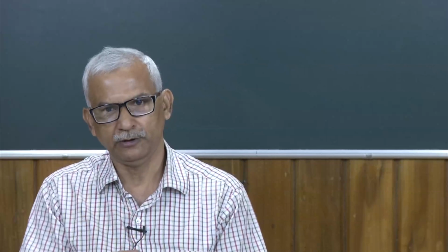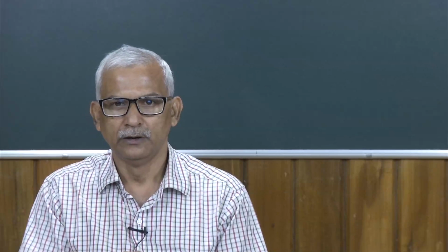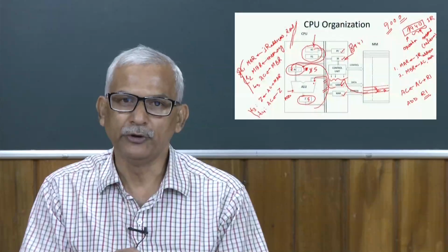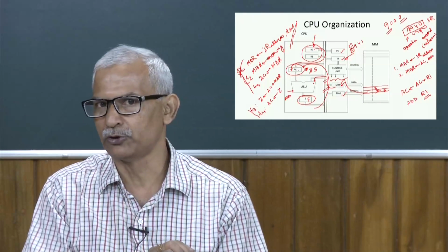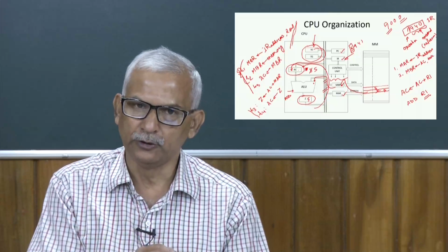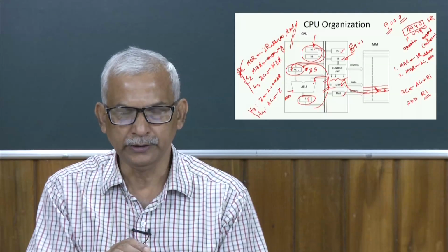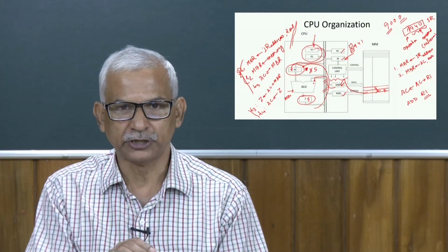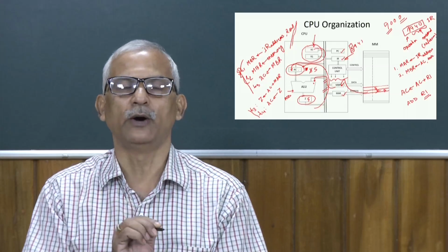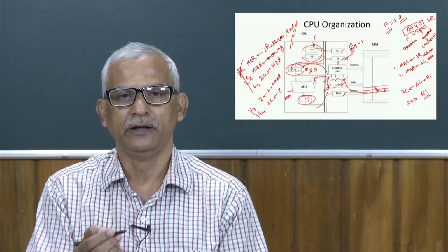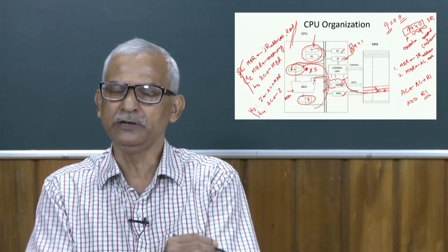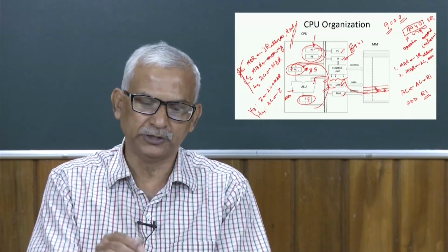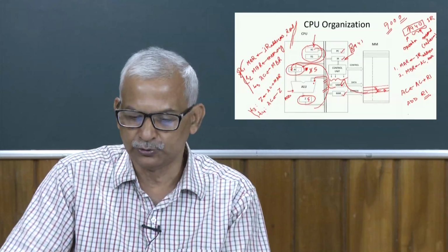One simple way you can think about how to implement it, maybe we can use a counter, which is an up down counter, because already we have discussed up down counter. So, we put the value. Once we are going to execute an increment instruction, what we are going to do? We are going to count up, and when we are going to implement a decrement operation, we are going to count down. So, that means value of R1 will be placed to the counter.